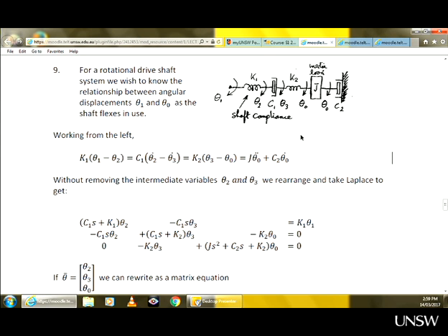So this inertia term will be equal to this torque minus this torque. If you ignore the rest, this inertia term equals this minus this, and this goes away. What's this term? That's due to this damper. Aren't they supposed to subtract each other? No. This and this subtract each other to be equal to inertia. So this and this are external torques. One positive, one negative.